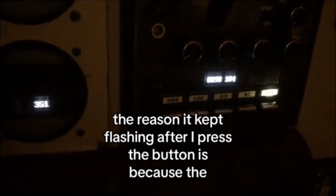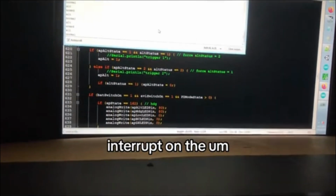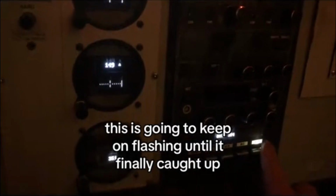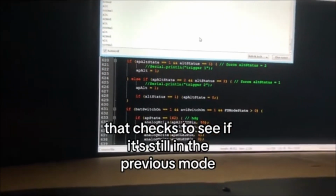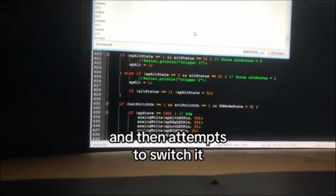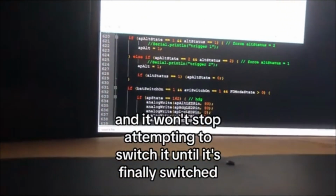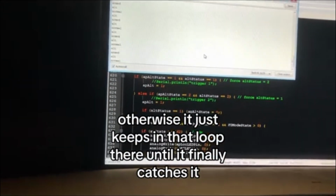So what happened, the reason it kept flashing after I pressed the button is because the interrupt on the Arduino board didn't catch this command. This was going to keep on flashing until it finally caught up with this entry right here that checks to see if it's still in the previous mode and then attempts to switch it. And it won't stop attempting to switch it until it's finally switched. Otherwise, it just keeps in that loop there until it finally catches it. That's my solution. It seems to work pretty good.